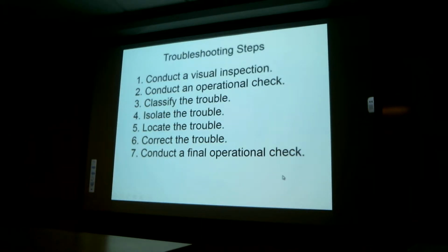and correct it. First thing you saw in the video was a visual inspection. Things that can be initially indicated as not quite right, you can fix. For example, that broken piece of safety wire or the fair lead that was on the opposite side of the control cable. We can fix some of those things, but we'll take note of that first and maybe make those corrections initially.